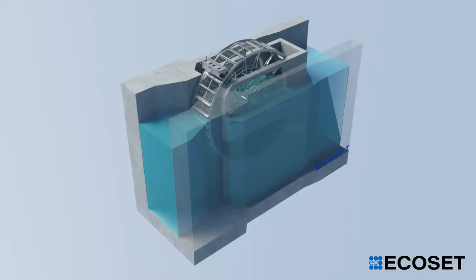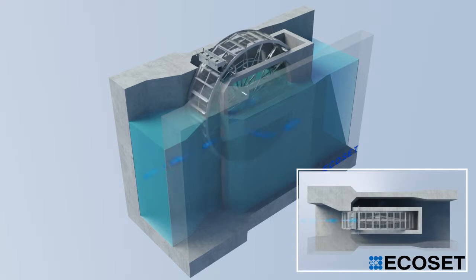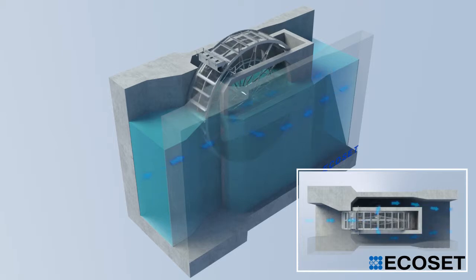As a standard control, drum screen can operate in manual operation and automatic operation, and there are 2 types of operating methods in automatic operation. One is differential level control and the other is periodic time control.